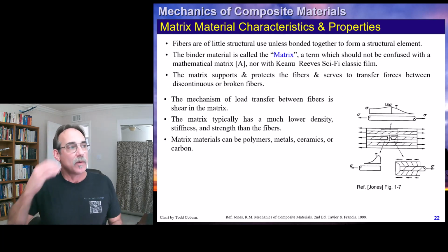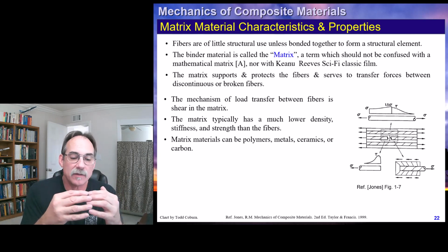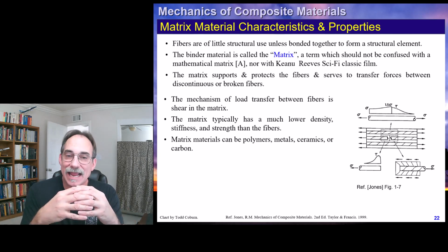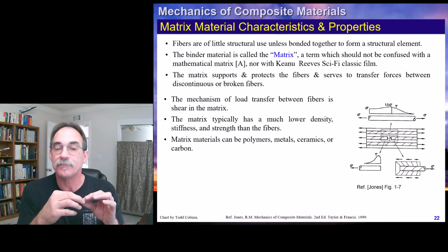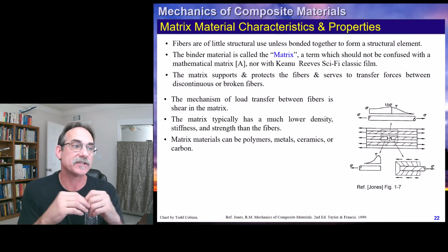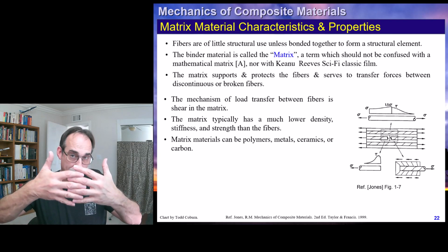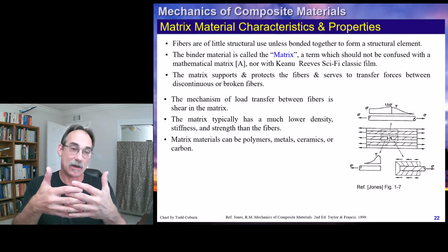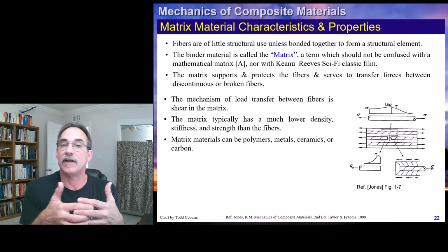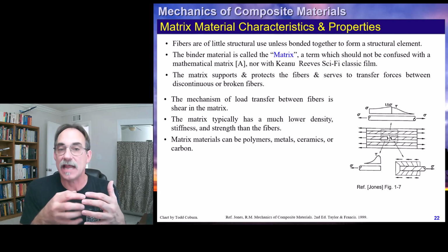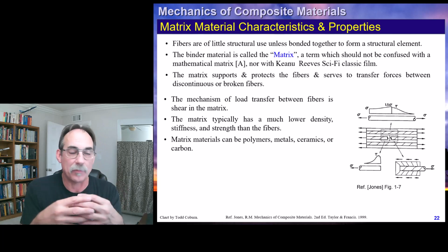Okay, this is looking at, so remember we're going to be taking the fiber and dropping it into the matrix. Now, as we talked about, these fibers, while they are long and continuous, aren't infinitely long, which means there are ends of fibers all over the place. This is one of the reasons why we need the matrix. So actually what that means is we have this impregnated fiber and there are ends in different places. Now, theoretically, if this is well created, these ends don't all align. Different ends could happen anywhere. At any given cut, you could have an end or multiple ends, but there aren't very many in any given spot because they're so uniformly prepared.